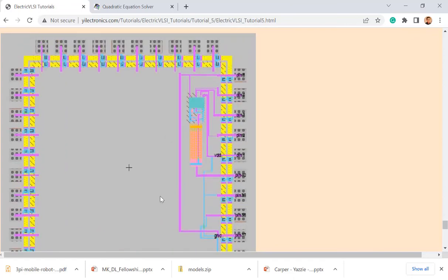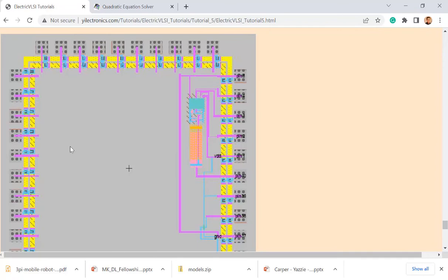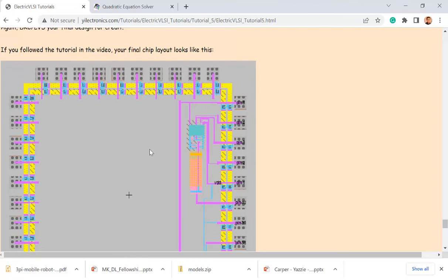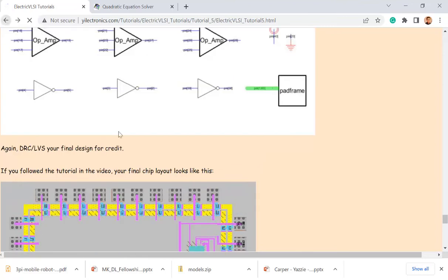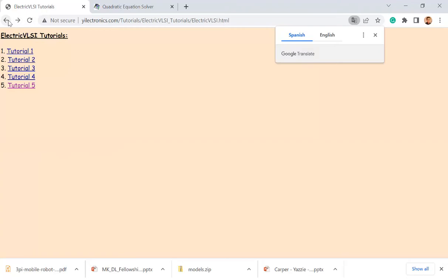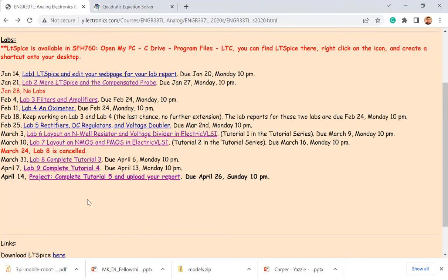So I hope you guys can put the ALU in the die frame, or pad, it's called pad frame. So these are the pads, and that's the pad frame. Just put the ALU here and make the connections instead of just stopping at the ALU. So you can understand how to put it into the pad frame. And after that, it's very simple. Just go to the toolbar and export that whole design into a GDS2 file. Get a GDS2 file from the whole layout and send it to the foundry and pay. They'll make a chip for you. That's it.